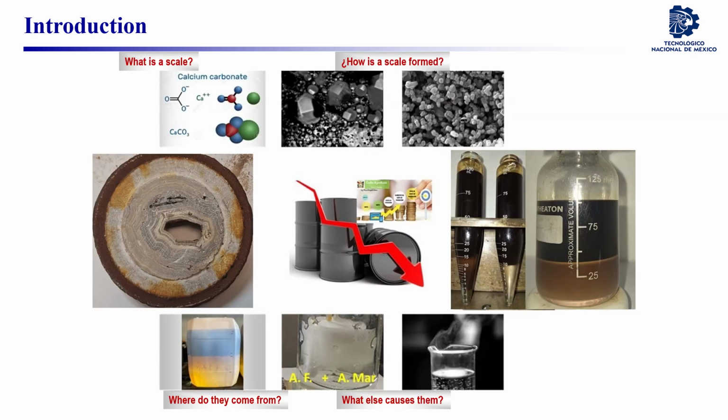Formation water is a byproduct of hydrocarbon production and contains high levels of dissolved minerals that form scales, starting from ion pairing followed by massive nucleation. It is also caused by the reduction of water volume due to evaporation, which decreases its solubility.